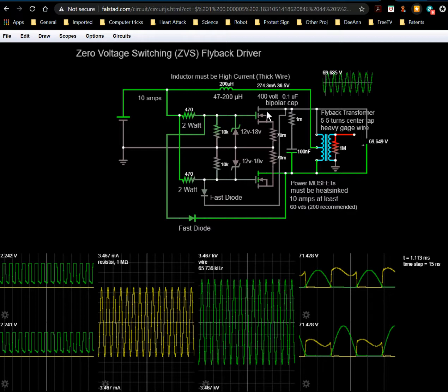Why is that? Because this transistor is turned on. That is connecting this point in this capacitor inductor circuit to ground through the transistor. So in other words, this is ground, and this is the capacitor with 69 volts on it, with positive here and negative here. That's forcing this to be 69 volts, which is doing what to this diode? It's making sure that it's reverse biased, because this right here is 12 volts, but this is 71 volts. So no current's going to flow through this diode.